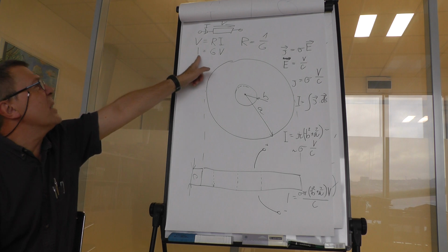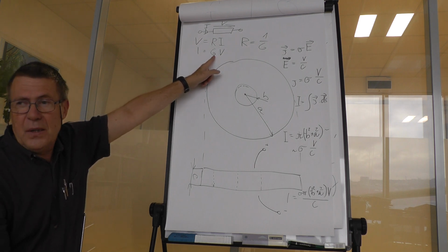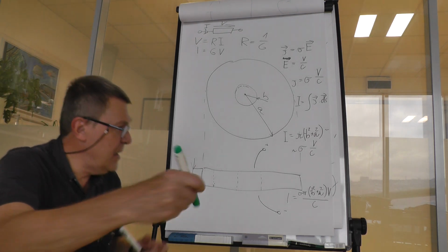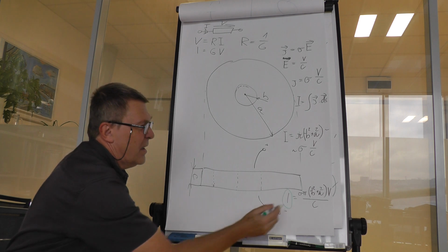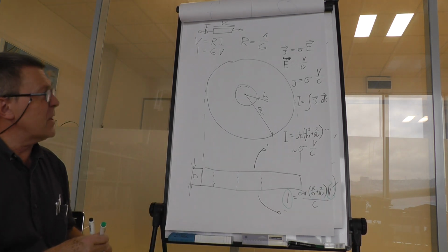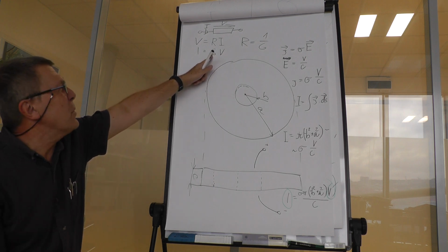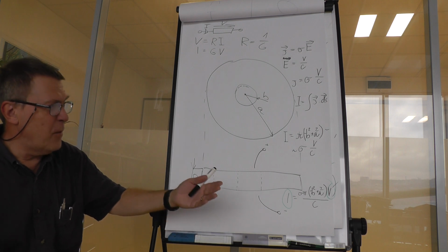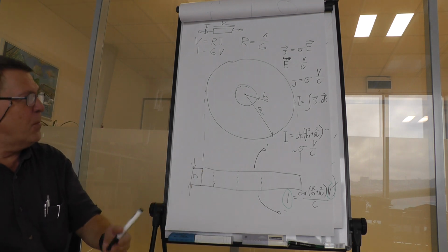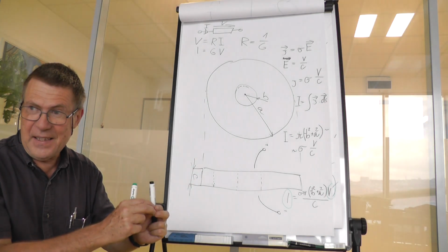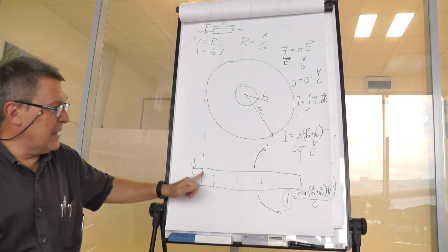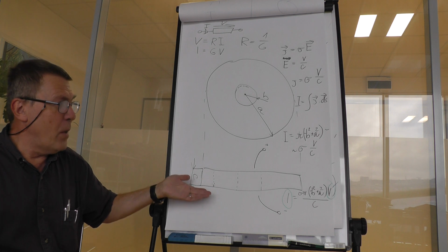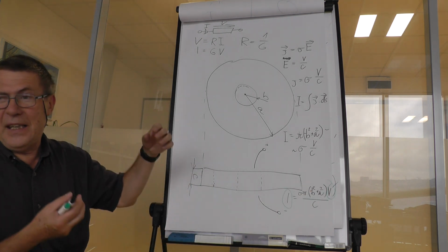Now if we compare it to this equation, current is equivalent to conductance times voltage. We have the equation just here. We can get current, we have voltage, and the rest of the equation must be conductance. And we can then easily get it out. So we have established a constant of proportionality between current and voltage. For this case, we have started from inside. We have been examining the electromagnetic field, that is the steady current field now, and we have arrived to an equation of proportionality between current and voltage at the outer terminals.